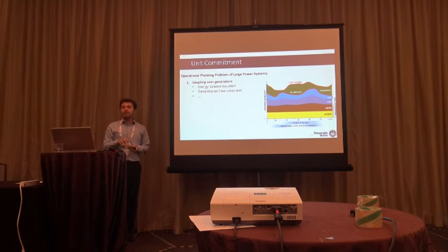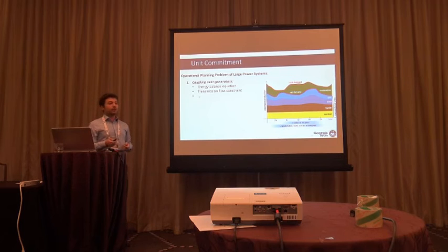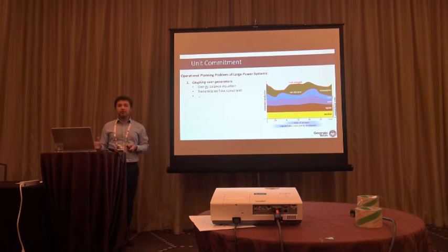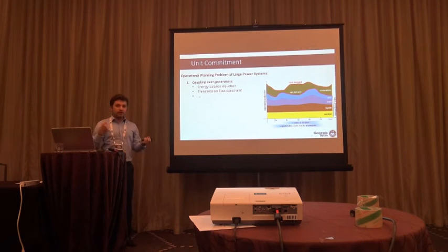The unit commitment problem is a very typical problem for operational planning of large power systems, and it's quite a difficult problem to solve from an optimization perspective as well, due to the large level of coupling that exists between generators and time periods, as well as the mixed integer nature of the problem. Here we can see there's a large number of couplings over generators. For every time period, the available generators need to produce the demanded electricity.